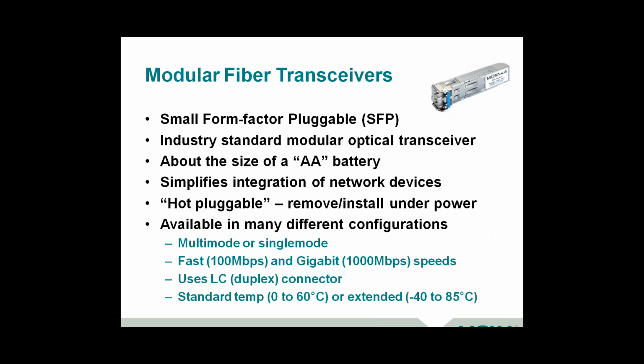Also understand that if you're looking at IT products, these are generally not to be used in industrial applications if you have anything other than a control room, because they're not certified for use in wide temperatures. One of the things that's kind of nice is that if you are doing systems level, Moxa does provide industrial wide temperature SFPs that are tested and assured to work in these challenging applications as a convenience to you. So it's important to understand the right product for the right application.